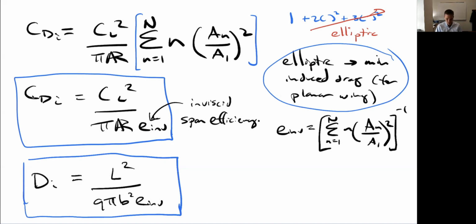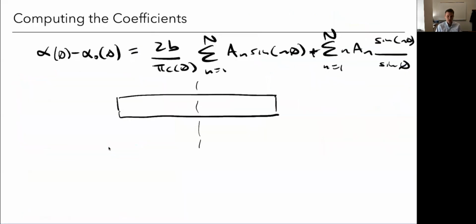Right, so here's that same equation. We've plugged everything in, and we have to use a collocation method. So what you would do, you could use symmetry, but I'll just show it with a straight wing here, without any symmetries. Let's say this is my midplane here. I would have to pick endpoints. So if I decided I was going to have 12 coefficients, that's what I needed to represent my Fourier series well, then I would have evenly spaced points here. I'm only going to draw 6, so let's just say I had 6 coefficients. Then I'd have 6 points. I'd evaluate this equation, so I'd have 6 equations and 6 unknowns, and I could solve for all of those. Okay, but again, we're not going to do that.